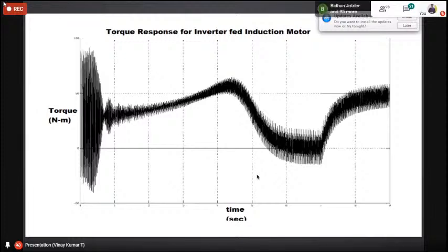Generally, there are two main reasons for ripple. One is the mechanical structure, the basic structure. The second reason is the control logic. By using control logic, we can reduce this ripple. Another technique is by changing the mechanical structure, by selecting a fractional slot machine, by changing the concentrated winding or distributed winding. On the machine design side also, by taking precautions, we can reduce this ripple. On the control side, by choosing different PWM techniques or different control techniques, we can also reduce the ripple.